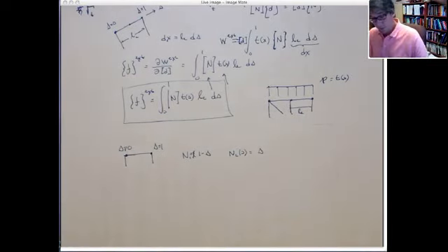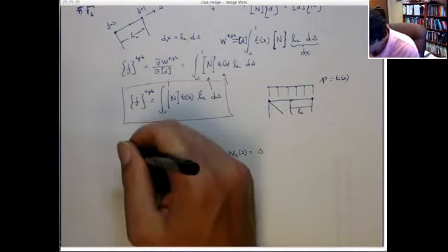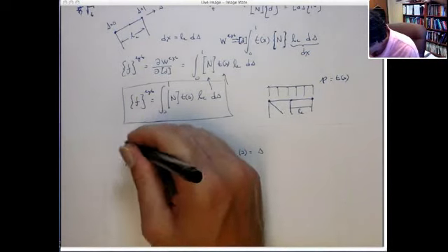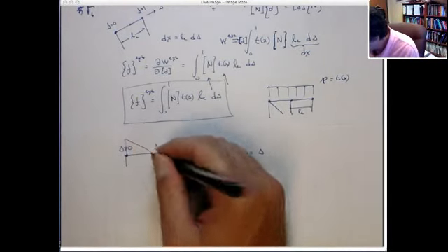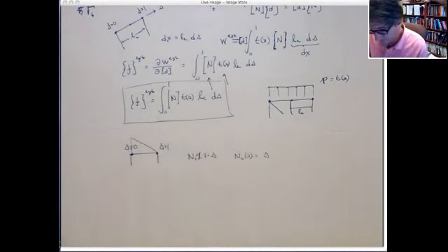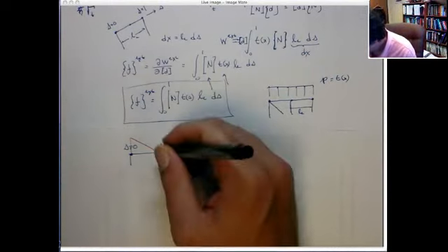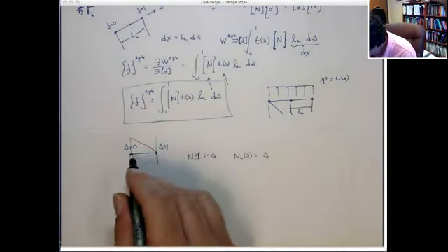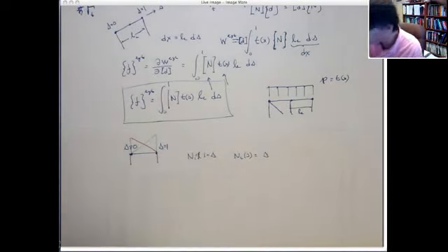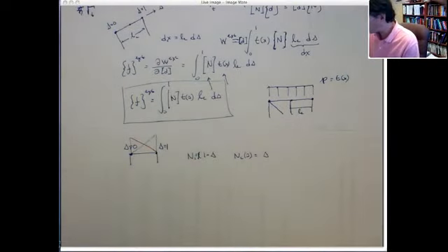All right? So if we were to look at the shape functions, you can see on this edge, N1 goes up to a value of 1 and then linearly drops down to 0. And N2 starts at 0 and goes up with a constant slope up to 1. All right, so those are the shape functions on that edge. We just really need to integrate on that edge.